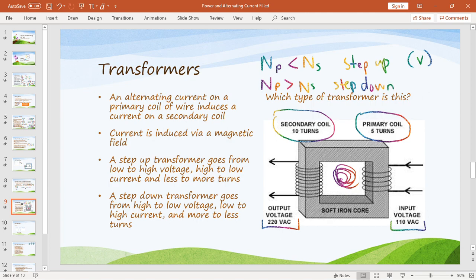And the idea is that when you go from your source to your long distance wires, then you step up the voltage, okay, and step down the current. But don't think of it that way, just think of the step up for the voltage only. And when you get to your house or your little transformer box or whatever you've got on someone's lawn, that's when you're going to take that high voltage and you're going to step it down for residential use.